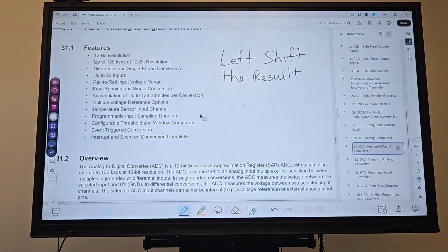The sample range is only 12 bits. The period register of the clock is 16, so you would have 4 bits. If we just transferred the conversion over to the period register, the 4 most significant bits would always be 0. It wouldn't give us a full range of what's available on the clock.